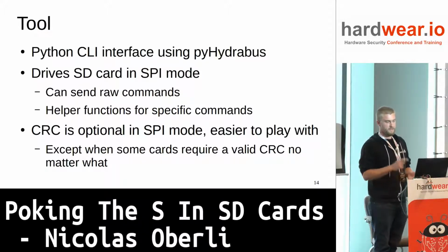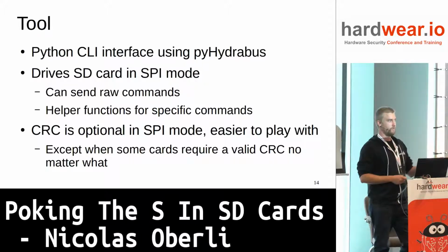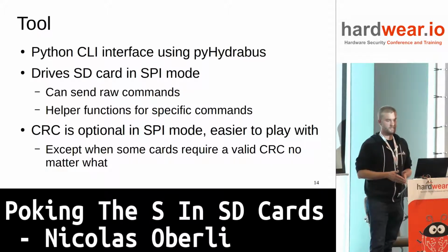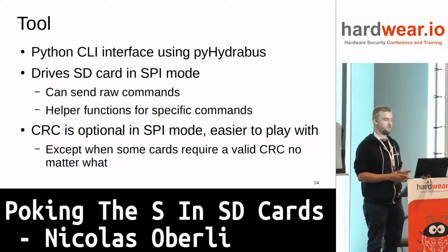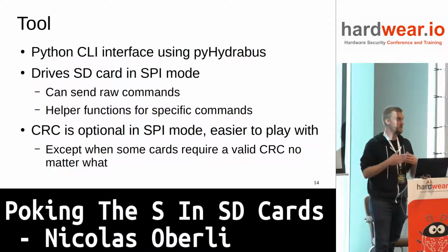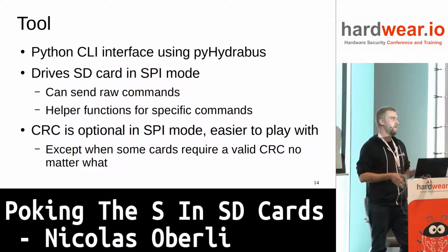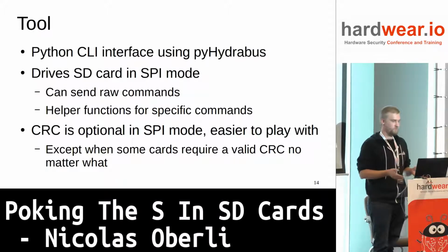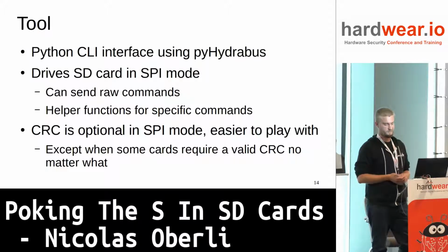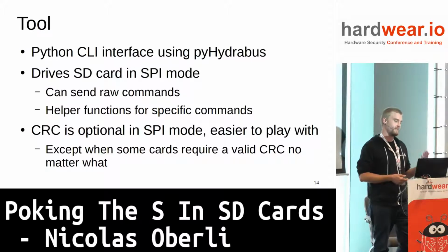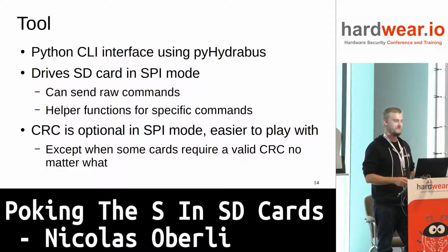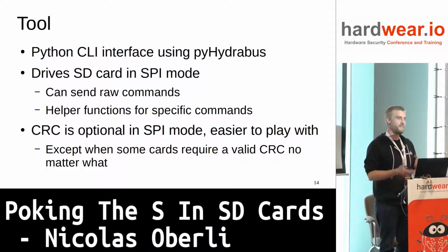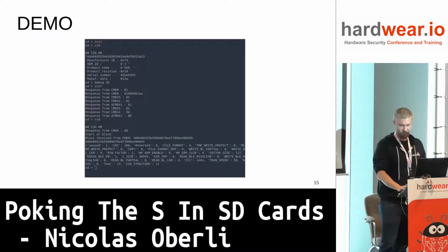One fun thing is that, as I said, all the queries and the responses contain a CRC. In the specs, it says that this CRC is optional. So you can just send zero instead of the CRC, and most of the cards do accept the commands, except some manufacturers that want the CRC to be in place. So depending on the cards, you don't have the same results. Again, really easy stuff.